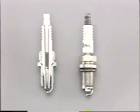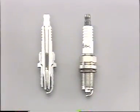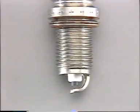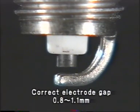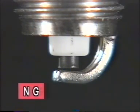The role of the spark plug is to reliably generate strong sparks and thus ignite the air-fuel mixture. The ignition sparks jump between the spark plug's center and earth electrodes. The spark voltage is high or low in proportion to the spark plug gap. Through normal use, the gap will increase, causing the engine to misfire during acceleration. Therefore, the spark plug should be inspected periodically to maintain optimal spark gap.